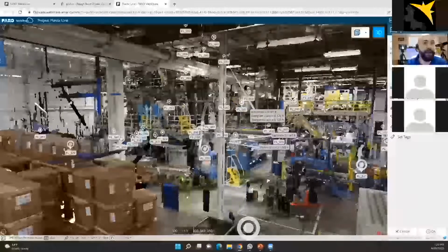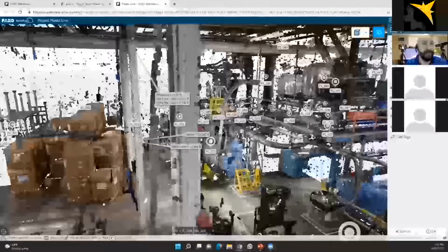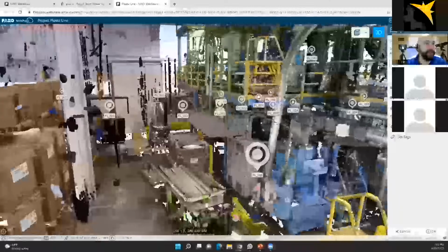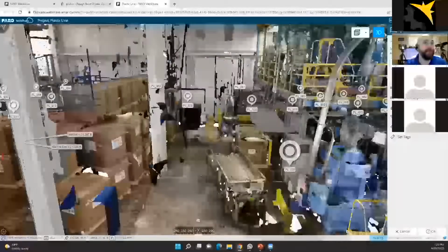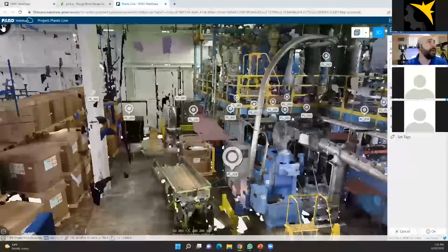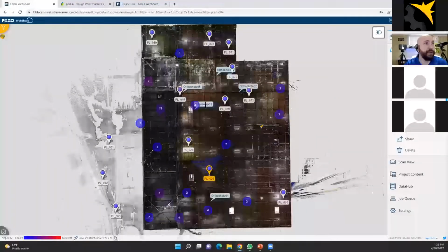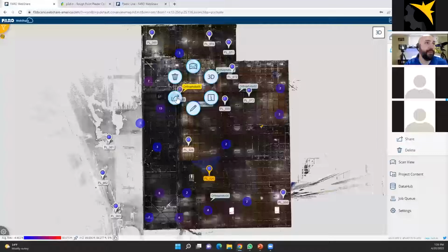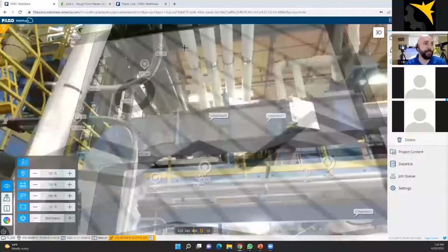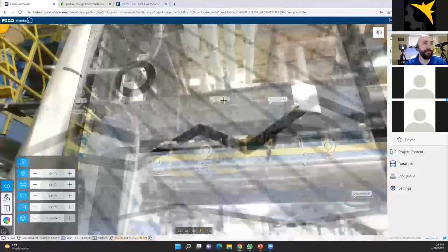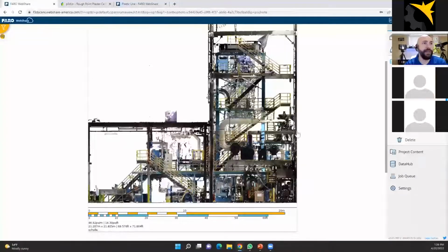Information can be shared in a 3-dimensional manner that pictures just can't offer. And so we can see all this and be able to capture that information. One other capability I really like to show is the orthophoto. You can take a top down or a front view and create an orthophoto from that information. So we can see that now this can be brought into our CAD platform. It can be scaled and then utilized to draw exactly what we need to draw right from this.